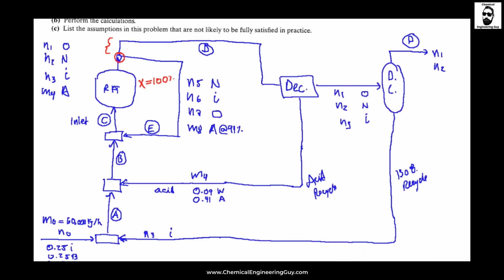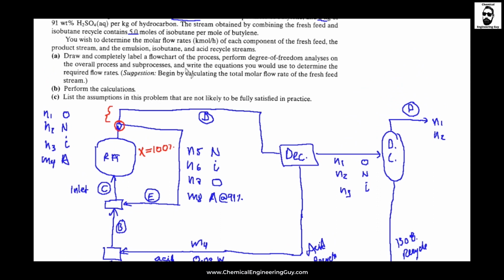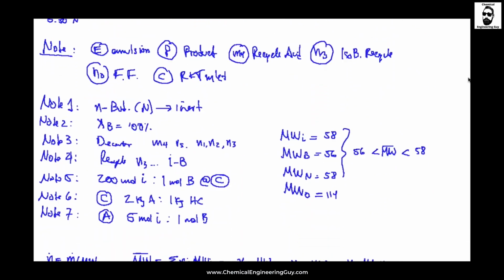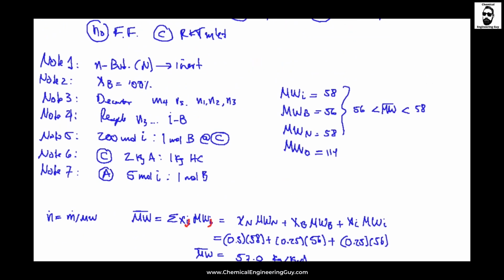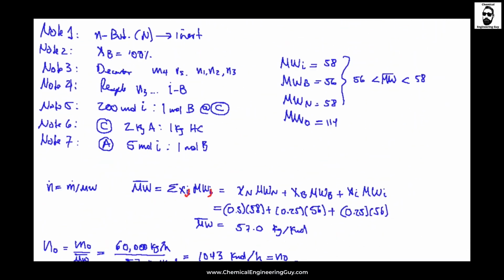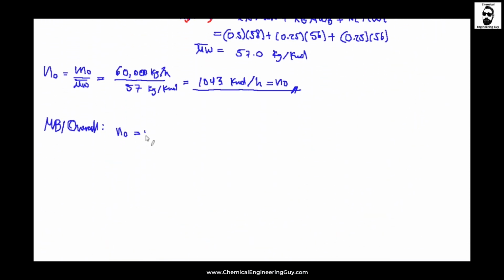And as you can see, we can already start solving this. They ask for the molar flow rate of the fresh feed. We have it right now, so we're good for that. We still need to do a lot, but it's good that we have this. So let's start doing more mass balances. Let me do a mass balance on the overall system. That's always a good idea. So that's essentially n0 equals n1 plus n2. I have n0, but I don't have n1 nor n2.